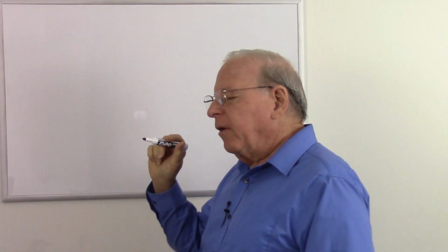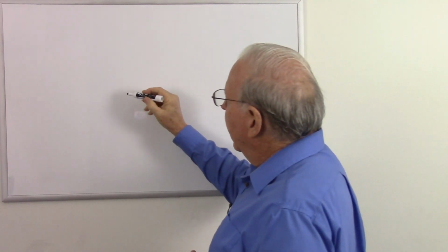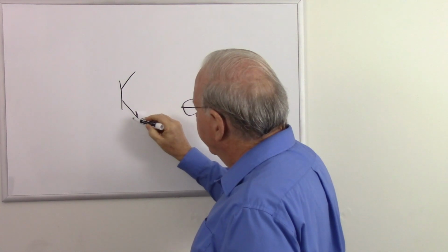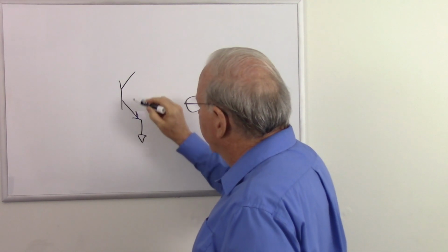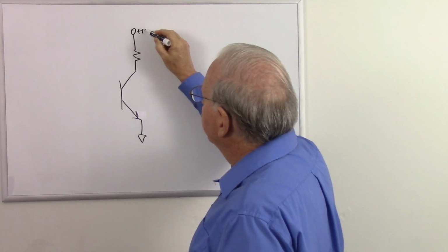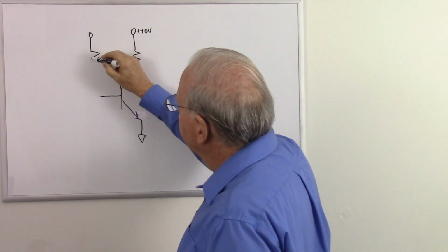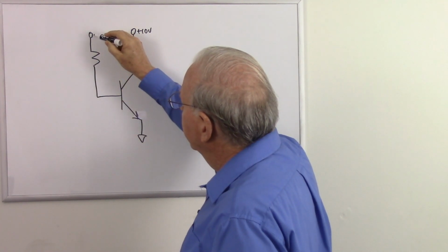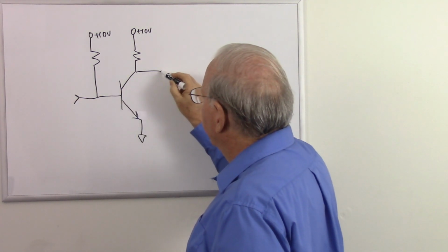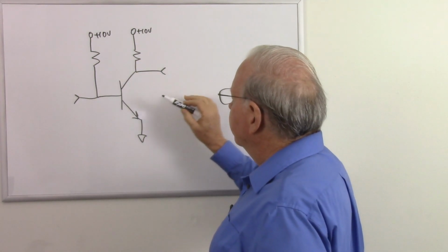When I started preparing to make this video, I started thinking about oscillator circuits and what the parameters were, and one thing I thought of was a simple common emitter amplifier, which satisfies the need for amplification. I'll make this about as simple as I can make it. Let's power this by positive 10 volts and have our bias resistor here. There is our input, there is our output, and careful biasing can make this a working amplifier.